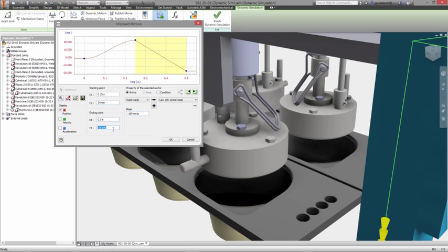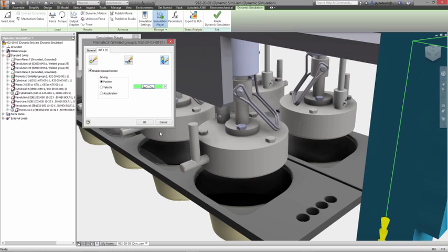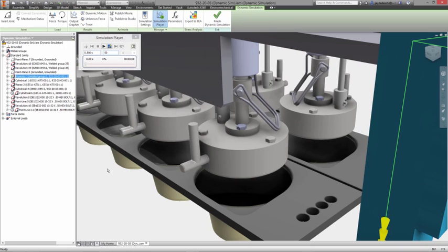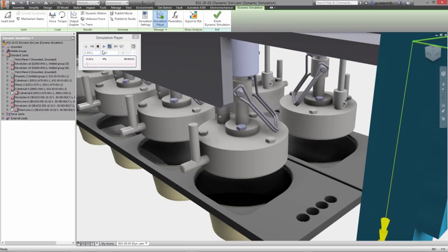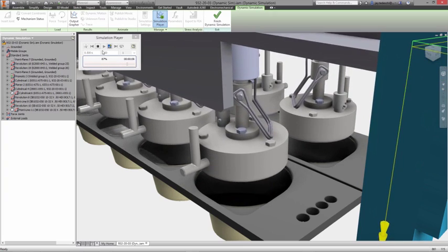Setting up this type of study is simple. Just describe the motion of the joints that control how the product operates. This can be done by setting the position for the joint at different points in time, with full control over the acceleration profile. You can also specify what will occur outside the defined profile, which is especially useful for equipment that operates cyclically, so results reflect operation between cycles rather than startup and shutdown.